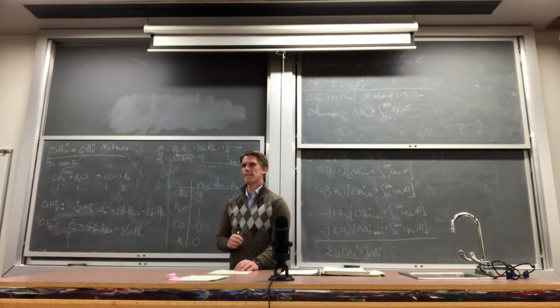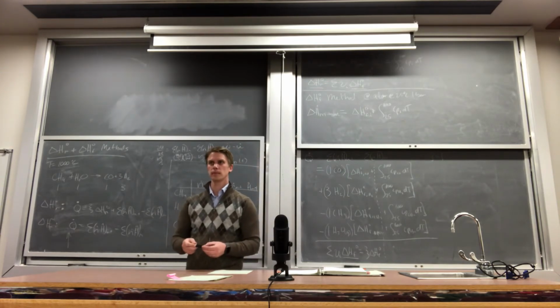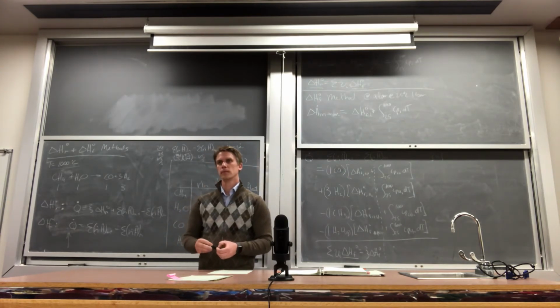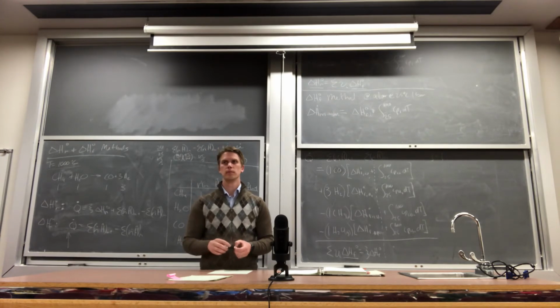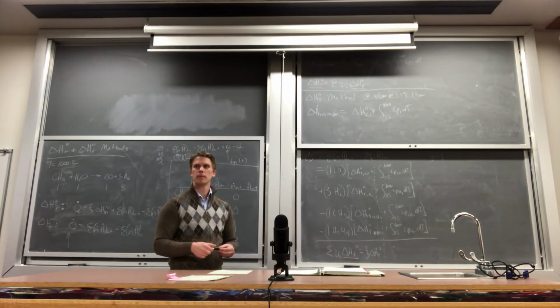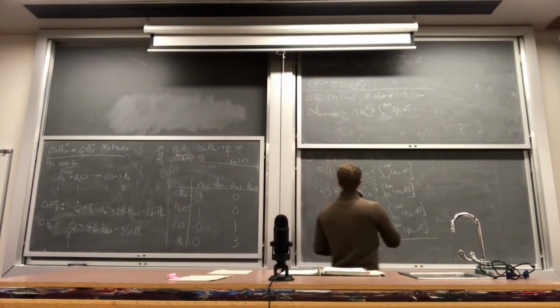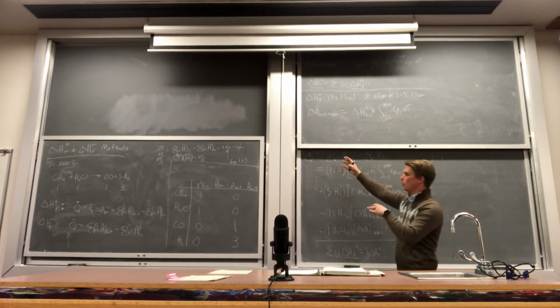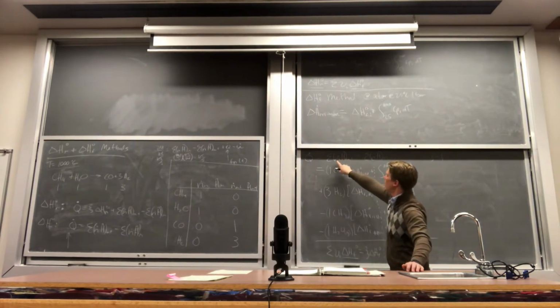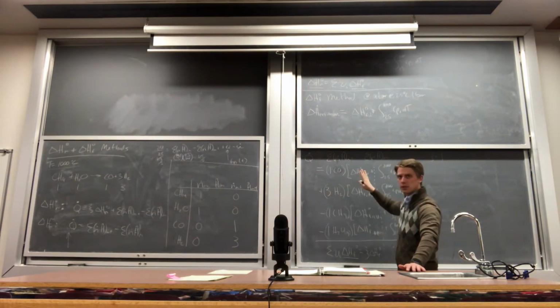Yes? So in the case where the extended reaction isn't one, you'd have those stoichiometric coefficients modified by the extended reaction somewhere. So in this particular example here, if we wanted to take it one step further, the n dot flow rate, the flow rate of each species in and the flow rate of each species out, that would change.